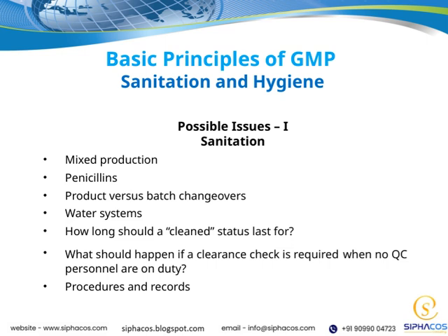Product versus batch changeovers are critical points. We need clear procedures to manage these transitions smoothly and avoid mix-ups. Water systems also play a vital role. Ensuring they are properly cleaned and maintained is fundamental since water is often a vehicle for contamination. A common question is, how long should a cleaned status last? That depends on the process, but it's important to have defined limits based on validated data.